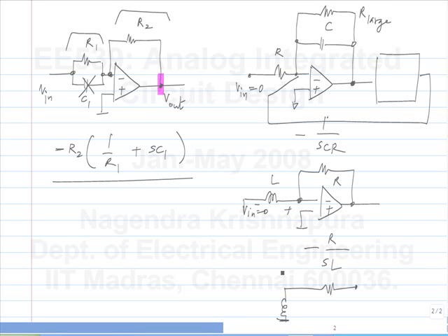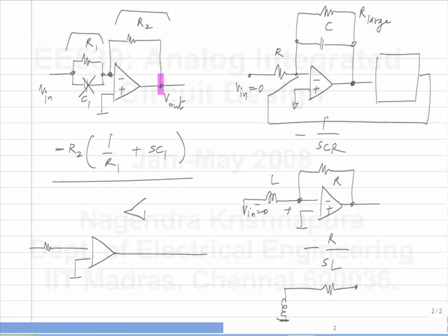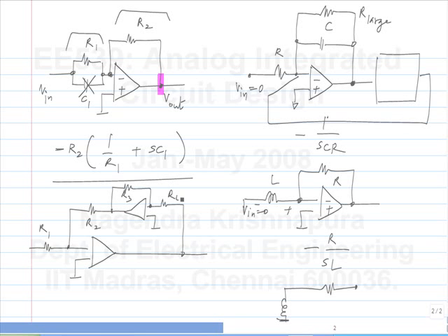Also there is the question of if you have multiple op-amps, it's not immediately clear which way the signs must be. So for instance, let's say I have a circuit like this. Just from designing the signal processing circuit, I don't need to put any signs because I know that this is a virtual short. The input of the op-amp is a virtual short. So you can go and try it out. What will be the transfer function between the input and output? Anyway, you go and try it out and we can discuss it day after tomorrow perhaps. And also which way to assign the signs to the op-amps, both of them.